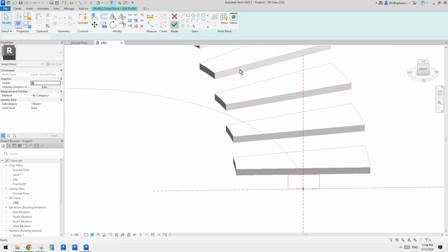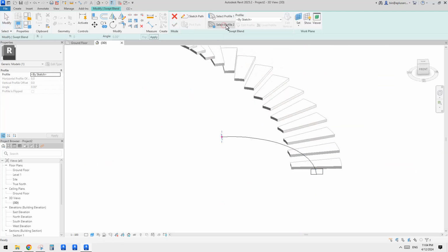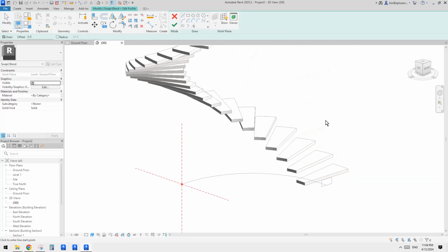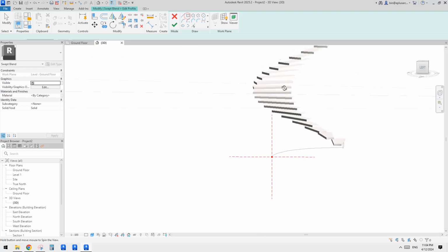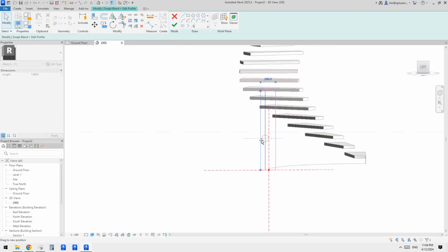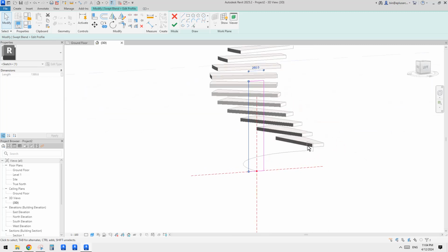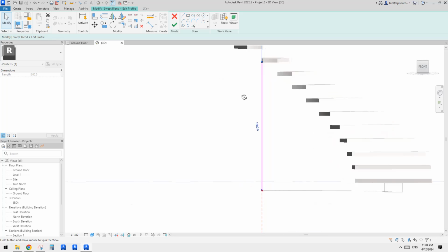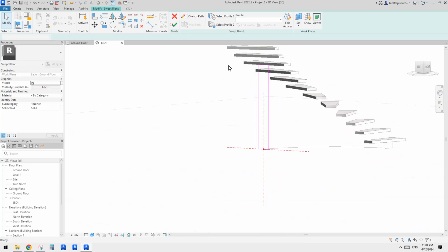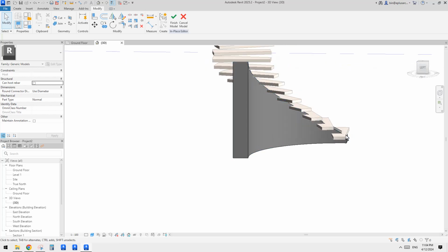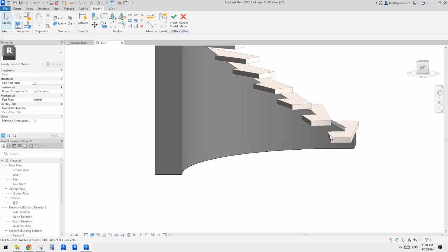Okay, and then finish, and then we can just click on select two, edit profile, and then we create another one. So for the second one, if we create the same width as the first one, but just change the height to match the stairs, so this will create the full height, right? So we might need to adjust this one a little bit to move this away from here. So move to here.